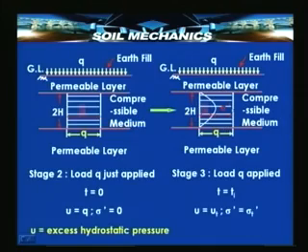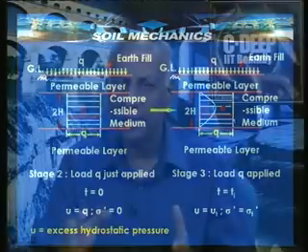The reason is, for stress to be transferred, water has to flow out. Flowing out of water depends on the availability of a pervious medium. Suppose we have two permeable layers, one above and one below, then at the contact with these permeable layers, the excess hydrostatic pressure will get dissipated immediately.